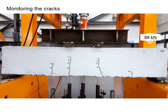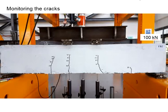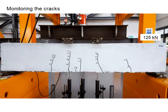Hold the load for 1 minute, take the reading, trace the crack, and mark the locations where the crack ends. You need to check every single crack to see if there is any further propagation. Let's say now we are at 88 kN load. These 3 cracks do not propagate further, while this crack ends here. Indicate the load level, and then you proceed with the next load level. You will repeat the process to observe the propagation of the cracks further.